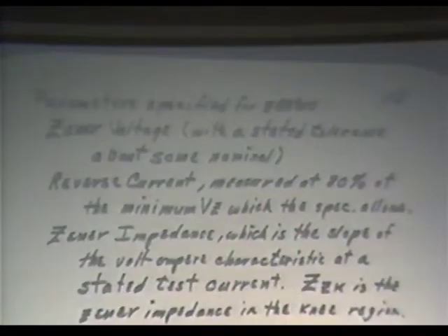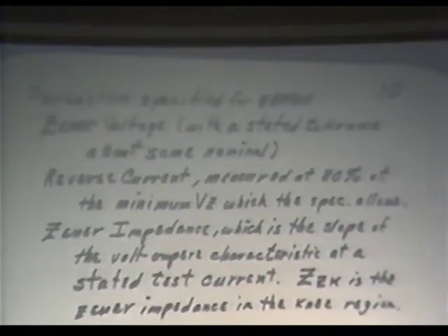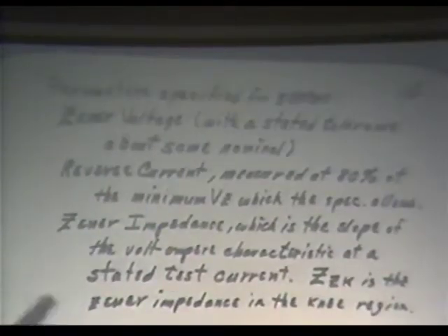Incidentally, it is also very difficult to get some people to test them if you decide that your circuit just absolutely won't work with anything less than a tenth-percent tolerance on the Zener voltage. Everybody's tester is cranked up to do lots of parts, not precision work. And it'll be somewhere between impossible and extremely expensive and very slow to get anything that's very tight, say beyond about 1%. You can, all you have to do is pay and wait, but those two things may be hurting a good bit before you get it done.